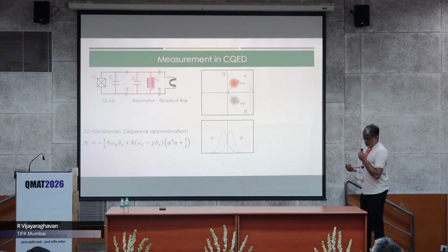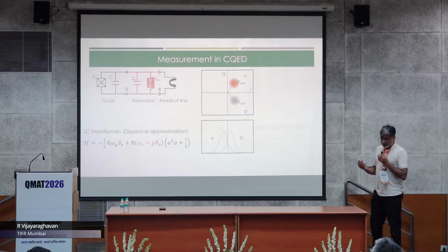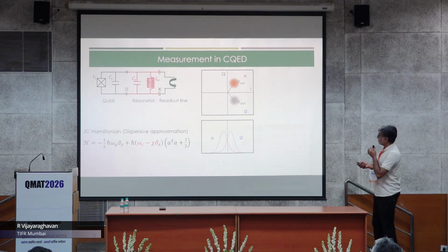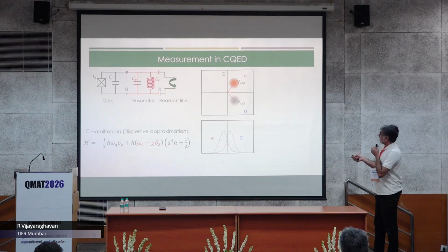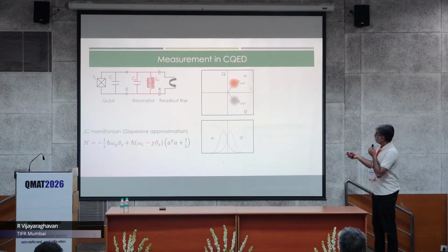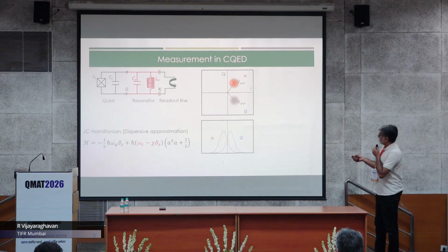So I had mentioned that the signal to noise ratio depends on several quantities, one of which is the drive. The idea is that you're now looking at these phasors in an IQ plane, the in phase and quadrature components. The two blobs here represent the noisy signal, and the means are in the middle. These two states are separated, shown as two different vectors. If you take a projection along one of the axes, you can draw these histograms.